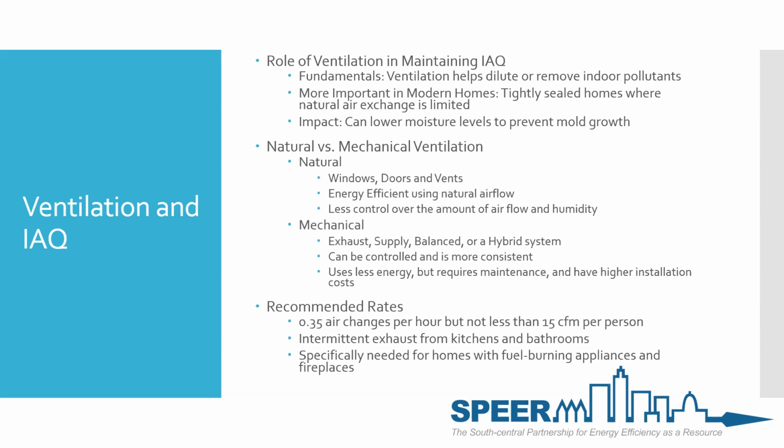Everybody agrees that yes, it does add to installation costs, but it's better for the house to do it that way, and it's less energy consumption. So in the long term, it's going to pay for itself in a relatively short amount of time compared to using an air handler as its fan source. Recommended rates you'll see out there: 0.35 air changes per hour natural, but not less than 15 CFM per person. A while ago we saw 62.2 is 7.5 per person, plus 1 CFM per conditioned floor area, whereas here it just says at least 15 CFM per person needed. And then intermittent exchange, exhaust in bathrooms and kitchens.